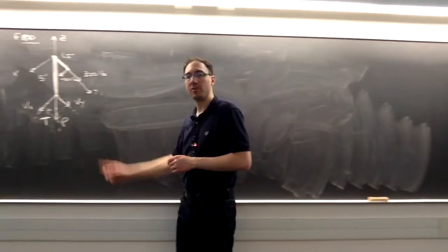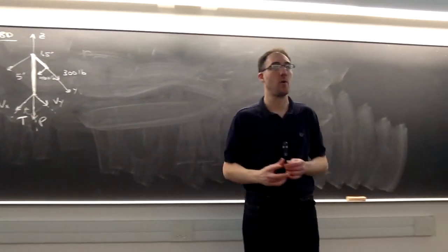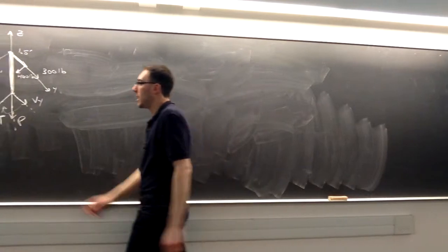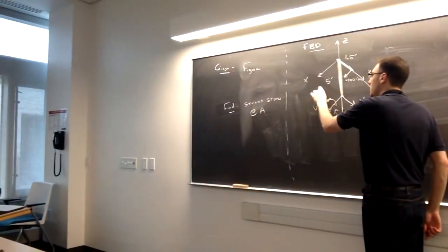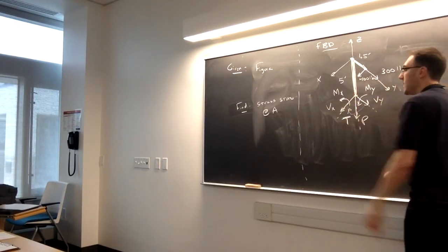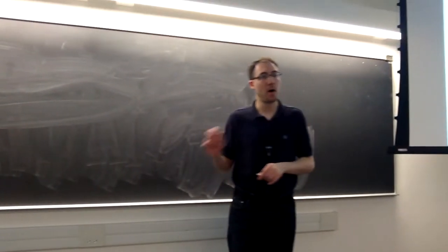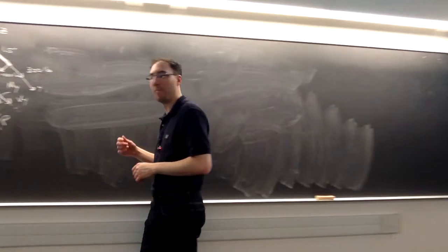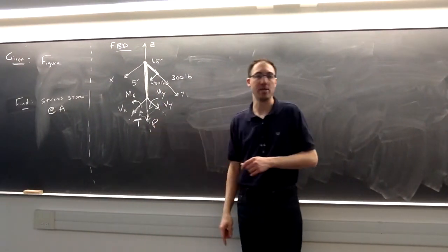Along with the 2 shear forces, there are also going to be 2 components of an internal bending moment, M. Those I can also assume are positive around those same directions. So I'll have an Mx and an My. Again, two components of internal bending moment, two components of my internal shear force, I have my normal force, and I have my torsion.